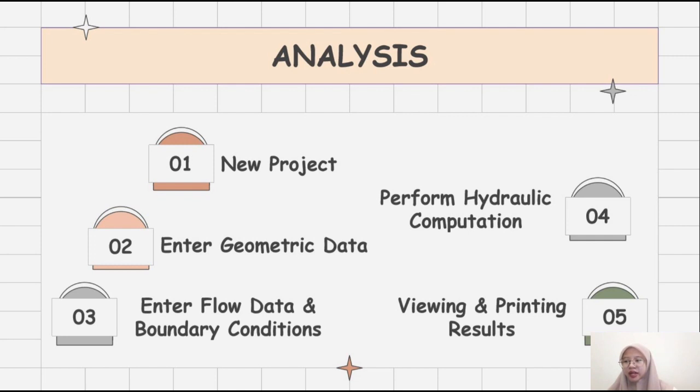Third, enter flow data and boundary condition. The edit menu bar option on the HEC-RAS main window contains the data entry form for steady flow data. To display the flow data for each river station, 3 profiles of 5 years, 20 years, and 50 years are constructed. Pressing the Reach Boundary Condition button on the steady flow data entry form will then display the boundary condition data entry form. The critical depth is the project specified boundary condition for both upstream and downstream.